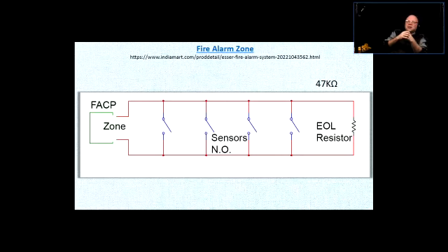Or something like that. Some other trigger point or zone could be connected also with 2 wires, and it could also extend along the same hallway. But to that one, you could have a bunch of pull stations connected. So if somebody pulls a pull station, the main panel would be annunciating that there is a pull station activated in such and such hallway. So it would be the name of the zone, right?